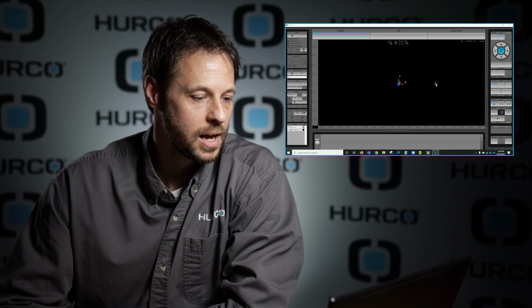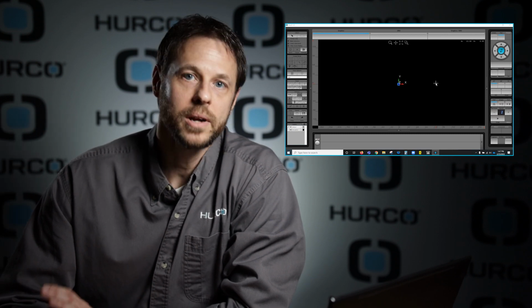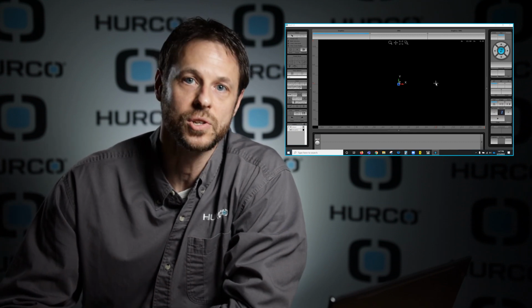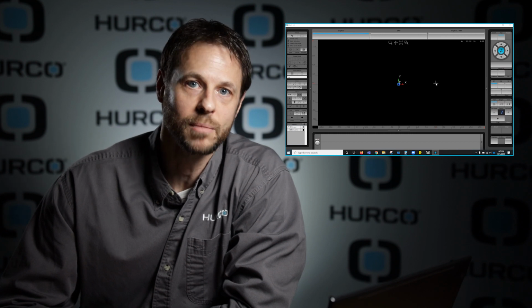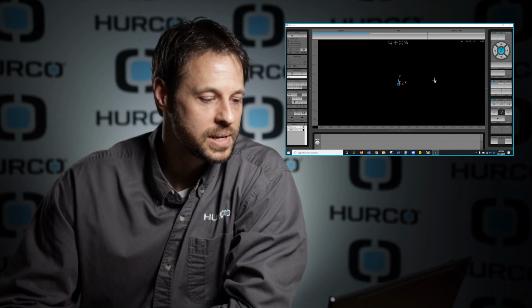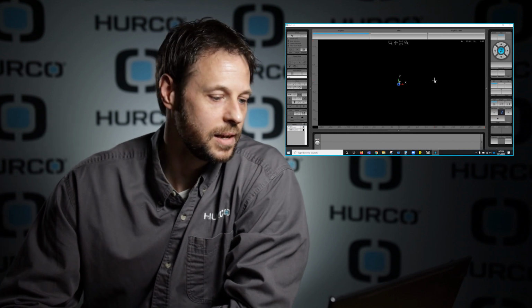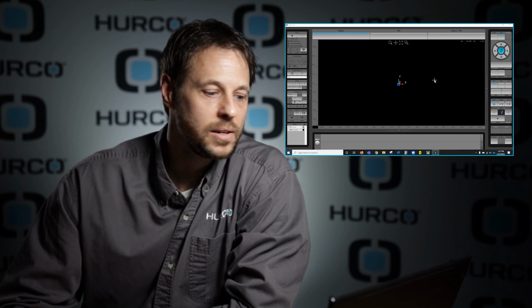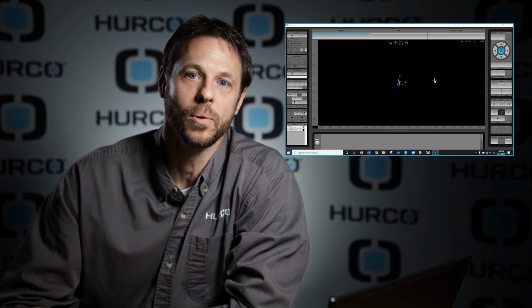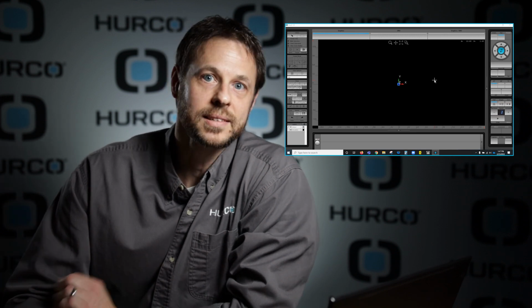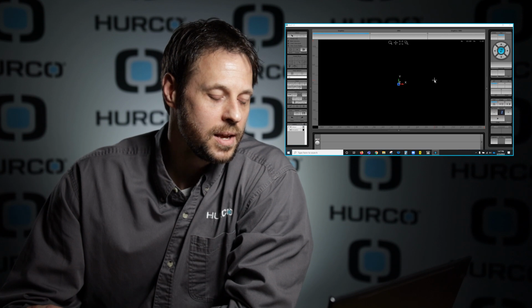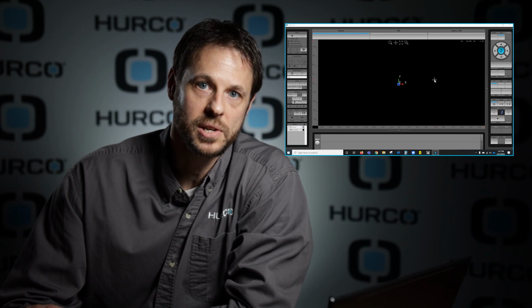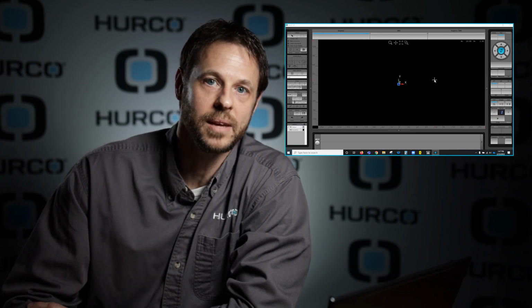So to get started, the first thing we should note is all we are doing here is creating a conversational program. These are just tools to work as a shortcut to generating the conversational data blocks that you already know how to work with. The reason I bring that up is if you are looking at a print and you see a feature that cannot be created conversationally, that feature cannot be created with the DXF, 3D DXF, or the solid model import. There is one exception to that, which we will go over in a later video. But for the most part, just know that if you cannot create the feature with a conversational data block, it cannot be created with the import options.